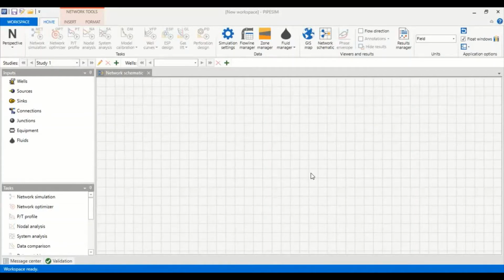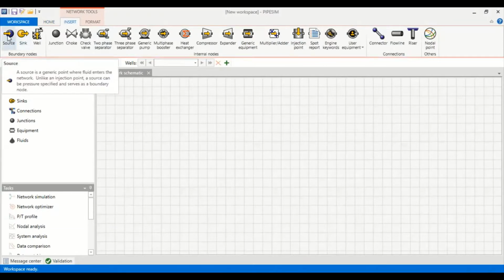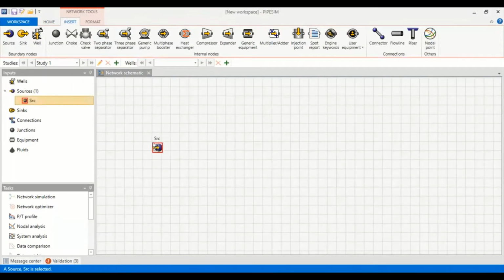So in this video, we will start learning about Pipesim network simulation. In Pipesim, we can perform well modeling and network modeling. So in this video, we will concentrate on the network modeling and network simulation. Okay, we will construct a crude oil pipeline. It will involve first the source: click source, and put the source here.